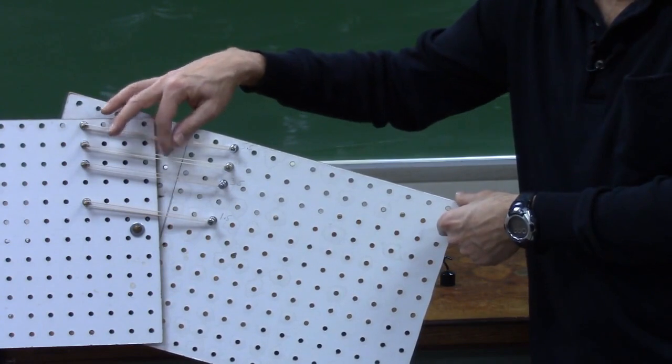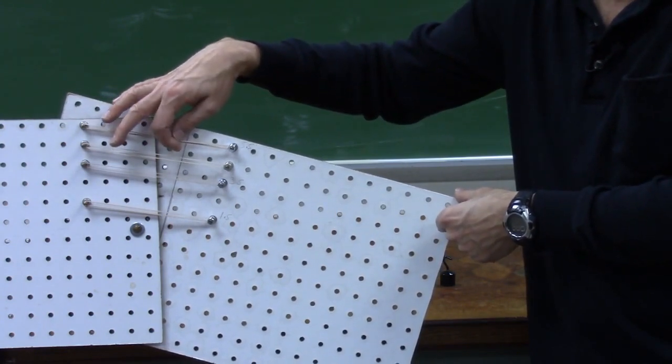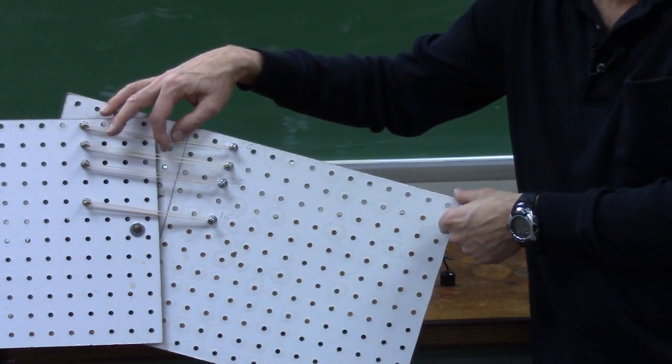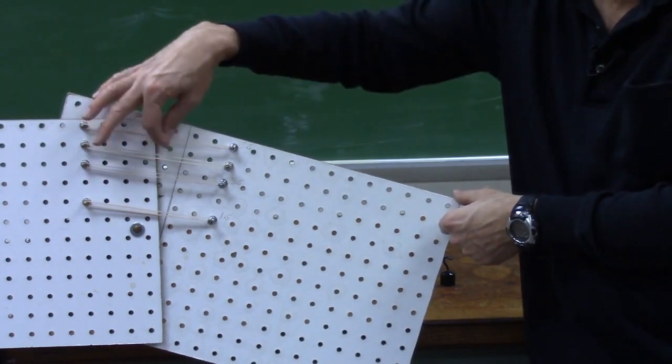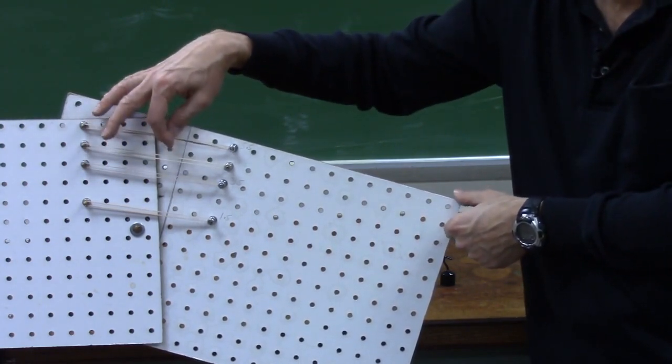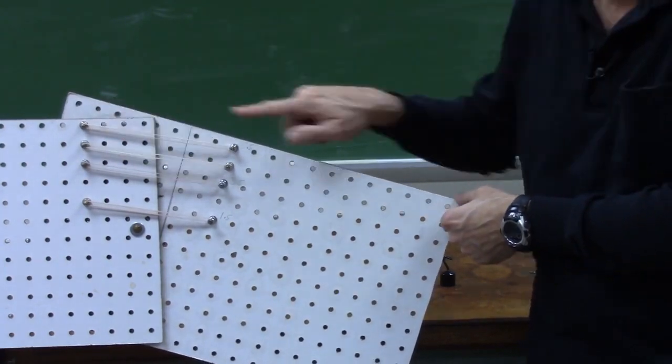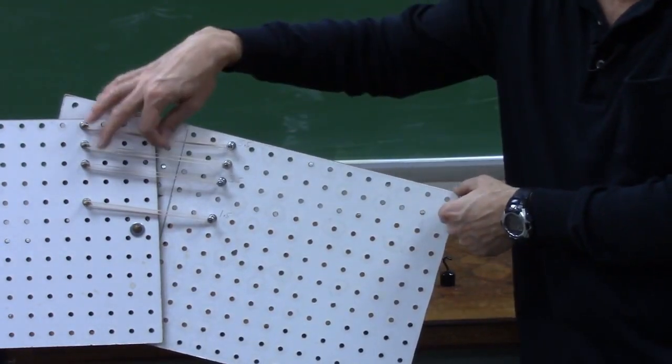And that's the key point I wanted to try to illustrate for you about the origin of this mysterious expression, the integral of y squared dA, or the sum over all little fibers of y squared times the cross-sectional area of that fiber. That's like the sum of y squared times delta A, where delta A is the cross-sectional area perpendicular to the axis of the beam of each little fiber that we envision.